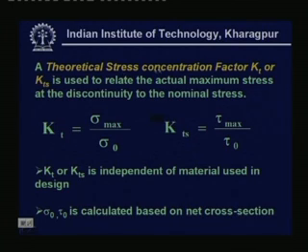This theoretical stress concentration factor, Kt, is based on normal stresses, and Kts is used where you get shear stresses, a situation such as torsion. So, where you use Kts. Now, this is used to relate the actual maximum stress at the discontinuity to the nominal stress.